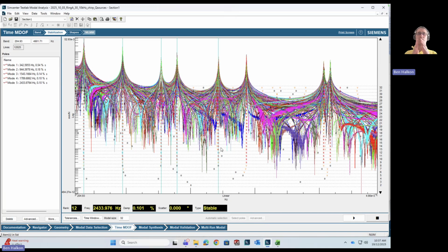The larger the asymmetries, the wider the frequencies are between these 2 split doublets that occur at these various frequencies. Not all of these mode shapes will be a split doublet. Some of them are m equals 0 modes, and therefore there's only one m equals 0. It's for m equals 1 and above nodal diameters, and above that you get split doublets.